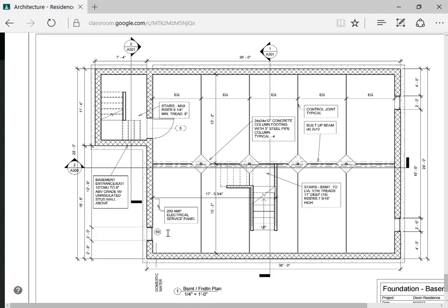So if I put a window up top of the wall and it's only 12 or 16 inches high, my cut plane for my floor plan typically doesn't show it. So what we end up having to do is, in our view properties, we have to change the view range for the foundation plan. Very often you'll bump it up to 6 feet for a cut plane instead of 4 feet.